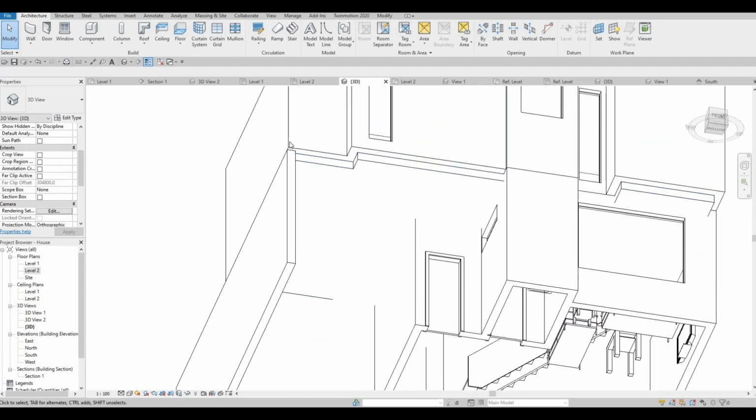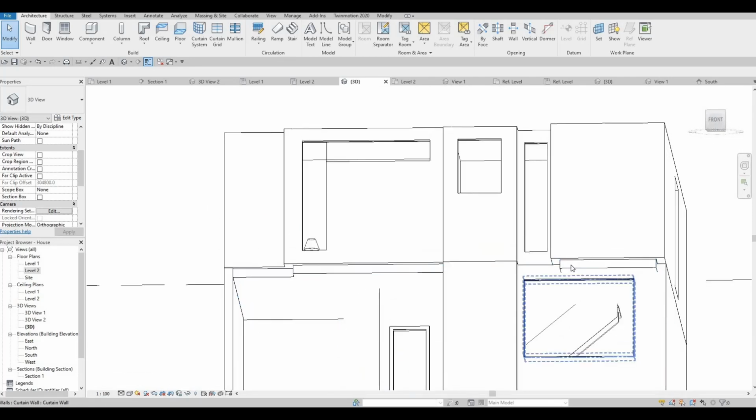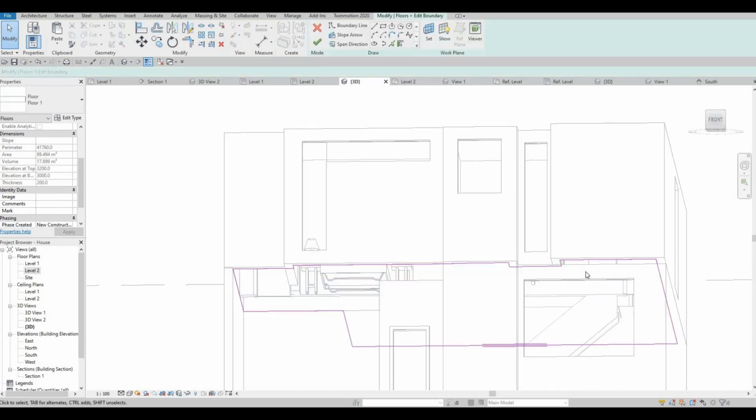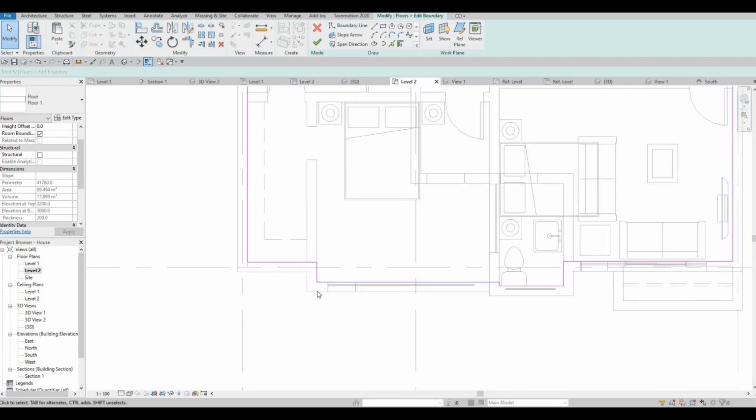I think it's better for me to go all the way here. The reason for that is this will be covered anyway, and then this one I'm gonna pull this back. So here it is. Use TR, trim and extend, and then delete the extra. So for here, I want to TR, remove this, and actually I could extend it here, EL.